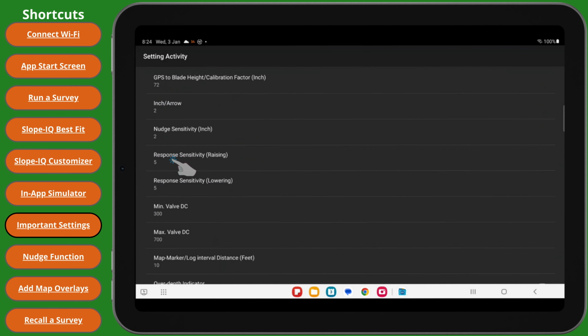You may also want to adjust the response sensitivities for manually raising and lowering the implement from the app. These relate to the raise and lower buttons on the grading screen. In this example, let's assume that holding the raise button doesn't lift the implement quickly enough. Tap on the setting to increase the hydraulic output.